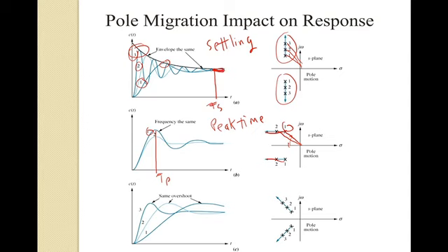And then finally, at the lower graph, notice the angle here for all of these is the same. So my damping is the same, meaning I have the same overshoot for all three of these cases. However, if I look relative to point 1, 2 is higher than 1, so I would get more overshoot, and 2 is to the left of 1. Let's reset on that. Sorry, I think I made a mistake.